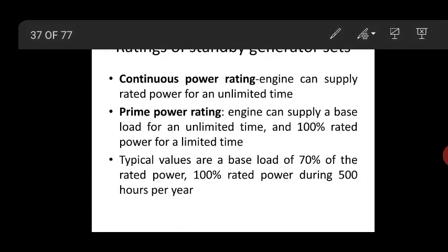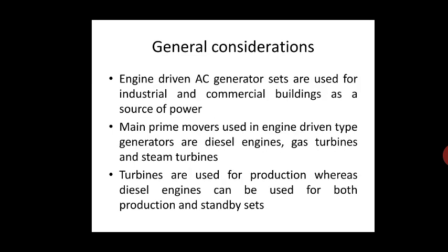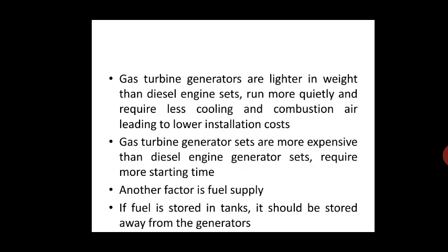That is why we prefer diesel generators over gas turbines. Of the two main drawbacks of gas turbines, that it is more expensive and requires more starting time, if you require more starting time, then there is no reason to call it standby power. Standby power should be supplied within 1 or 2 minutes. Okay.